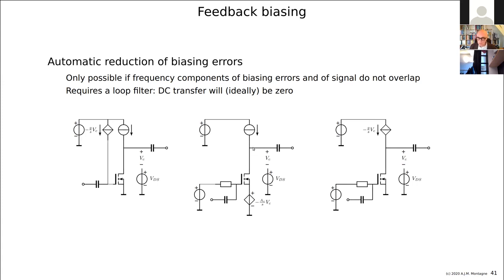In this case also, because the transistor is part of the loop, you will immediately detect it with a DC voltage here. So a correct operating point is then telling you that your amplifier will probably work. But here, the correct operating point is not telling you that the amplifier will work, because this control loop is local.